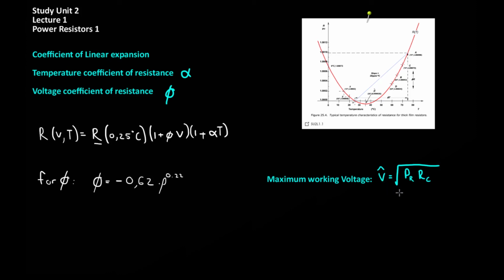Another way that this can be thought of is that in some family there will be some critical resistance where the voltage which develops over the resistor is not limited by the resistance or the current, but by the maximum working voltage. Above this voltage, flashover will occur where electricity will literally jump from one terminal of the resistor to the other. Once again, the maximum working voltage is defined empirically and may be defined differently for different types of resistor families.